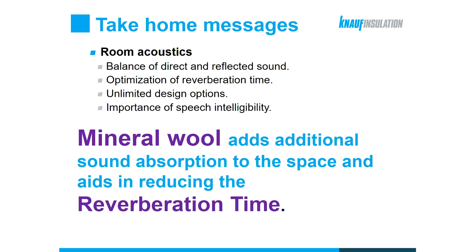And here are the important messages related to room acoustics. We've mentioned the importance of the fine balance between the direct and the reflected sound. We have discussed the need to optimize the reverberation time, keeping it a bit shorter for the spoken content and a bit longer for the music. We have discussed some strategies on how to control the reverberation time and presented unlimited design options. And finally, we've mentioned the importance of speech intelligibility in large public spaces and the advantages that wood wool solutions can offer in such applications.